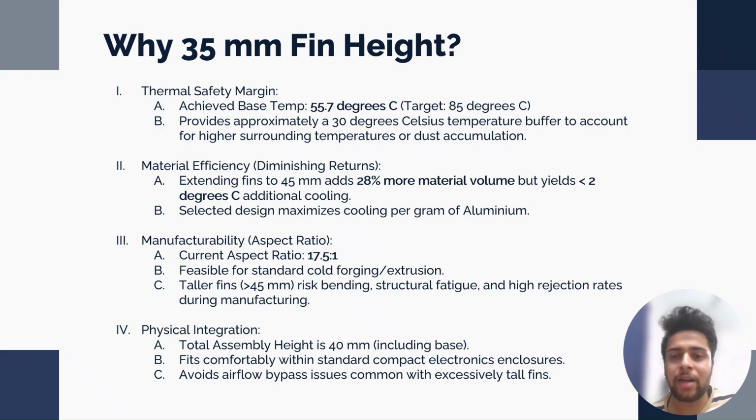Third, increasing the height more than 35 mm would increase the aspect ratio more, and this would risk the fins to be bent, have fatigue, or also have structural failure. And finally, having very large fins would not be suitable to be mounted in standard electronics enclosures. Thus, due to these reasons, we chose the fin height to be 35 mm.